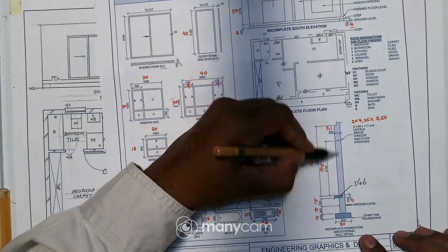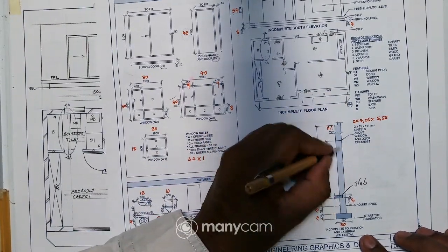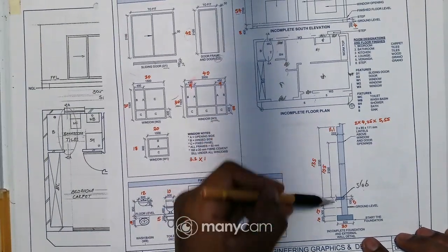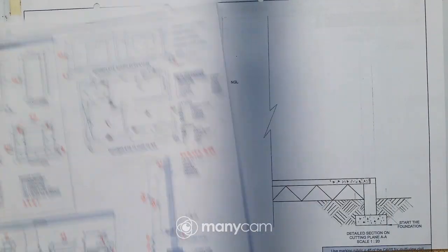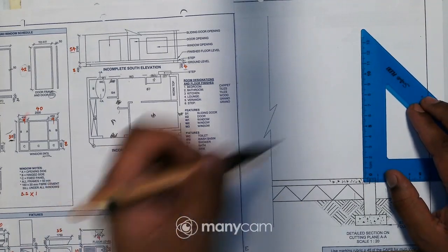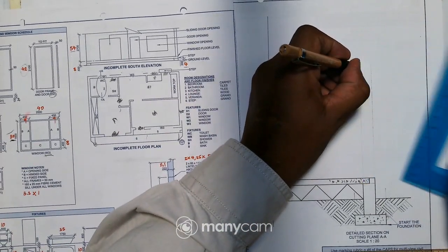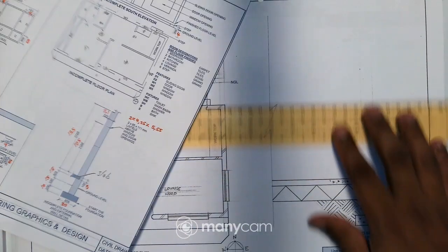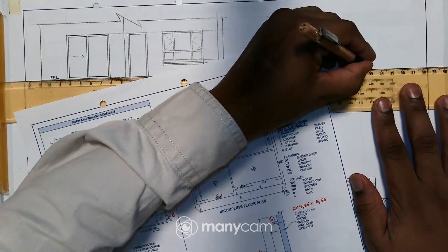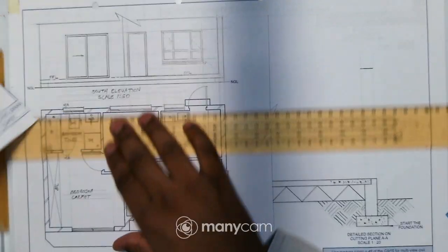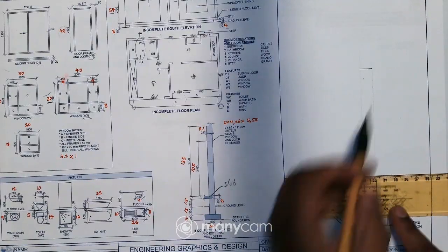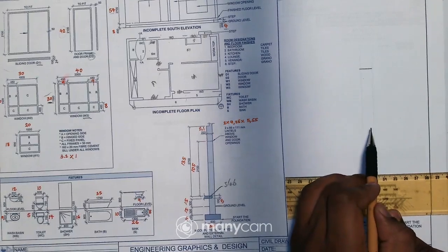And then I'll just draw the height of the window. Maybe the window will be from there to somewhere down here, right? So now from here to there, I'll measure 105. So it's 105 from the floor level. 105 is right there. Okay. So I'll just draw an outline there, a solid line. Okay. So that's where the window starts. So now I'll just draw the window frame going down, right?